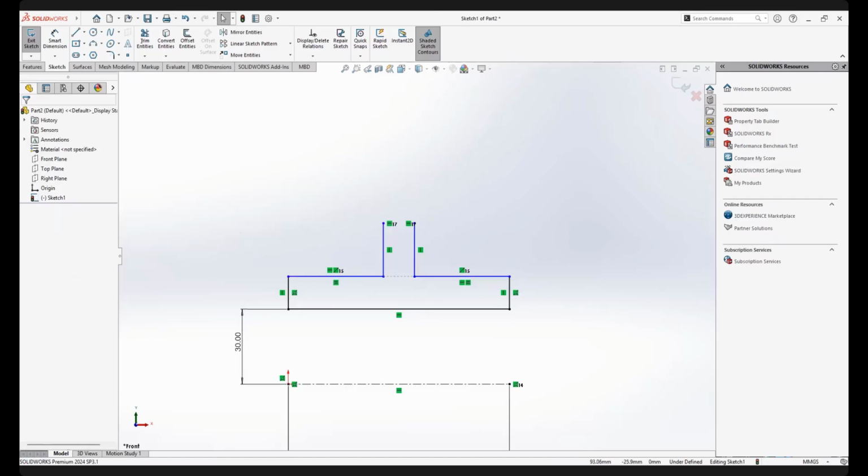Okay, if you look at the dimension, I cannot share it with you. The dimension shows that the thickness of this is 60 minus 75. I hope you understand me because it's hard for me to share on the screen. Because the radius of this one is 30. What is the thickness here? Then you play with the dimension. If you know the question, 30 minus 70, since the radius from here to the center line, 75 is the diameter. So the radius is 75 divided by 2, which is 37.5, minus 30 will be 7.5.